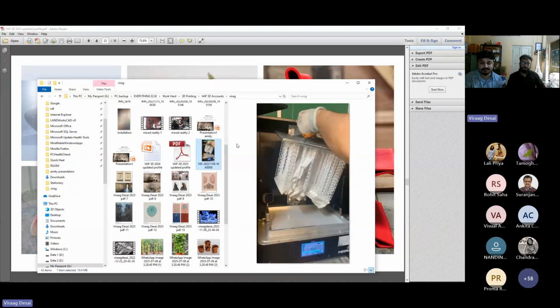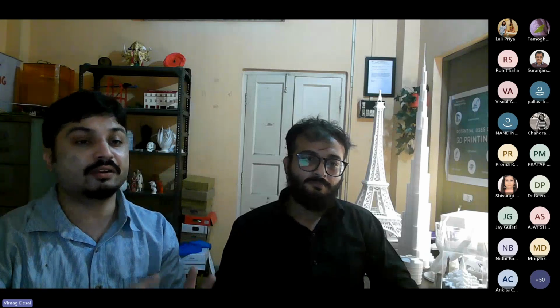It's a highly expensive material, but you can print in wax and then go through the process called lost wax casting. It's one of the oldest. In fact, I think it was invented somewhere here. It's where you take an object in wax, you cover it with some ceramic protective coating, like layers, and then you melt the wax out, and then you pour metal in, and then you get a metal object.